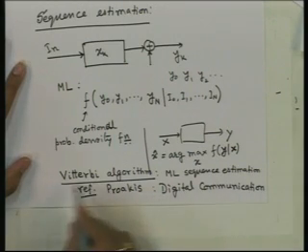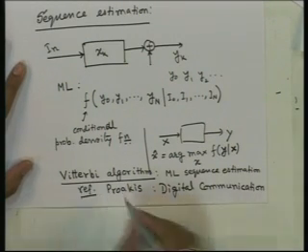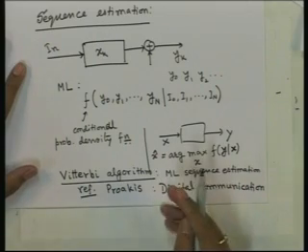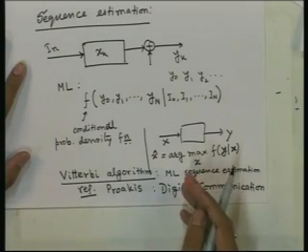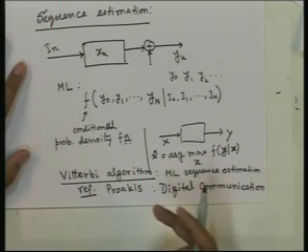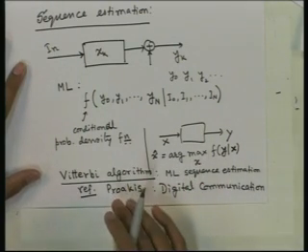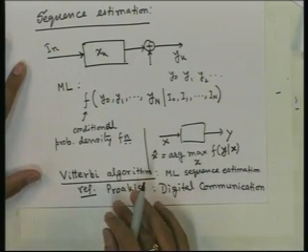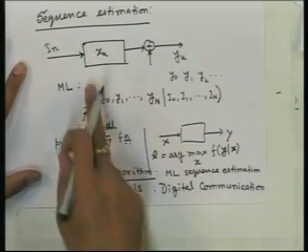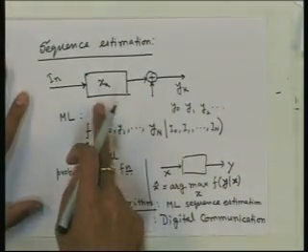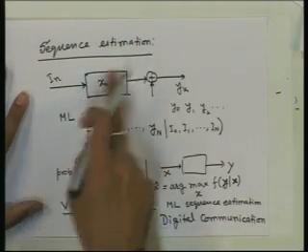And the same concept of this Viterbi algorithm is not only useful here, but it is also useful in decoding of a family of codes called convolutional codes. It can also be used for block codes, but it is especially famous for convolutional codes, where something like convolution happens, something which is happening here in the channel and the whole equivalent system.